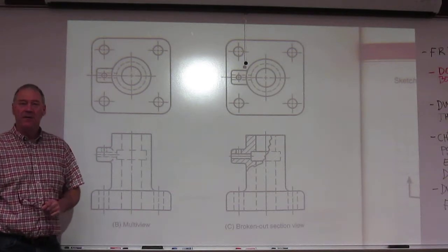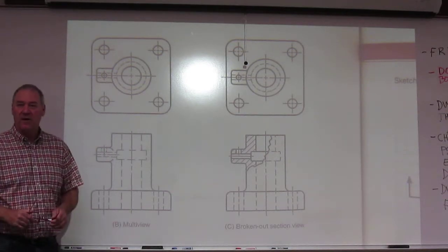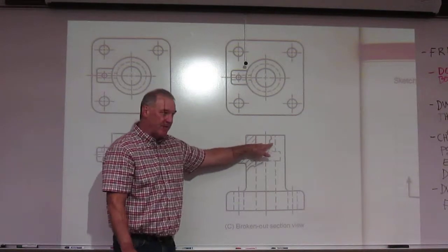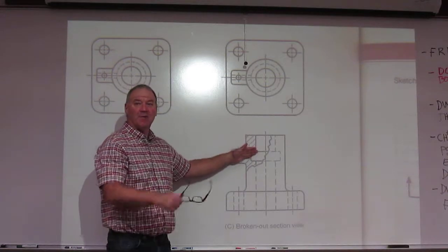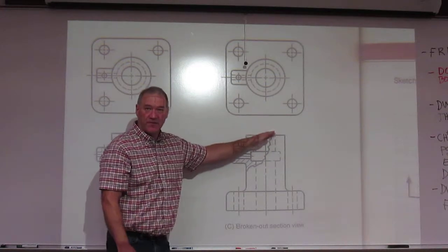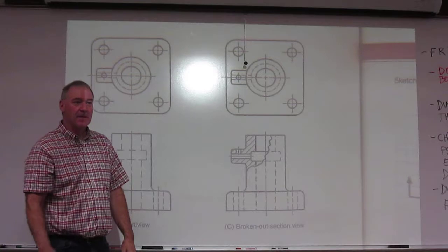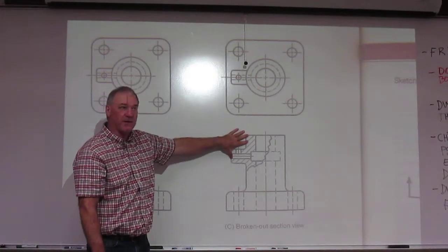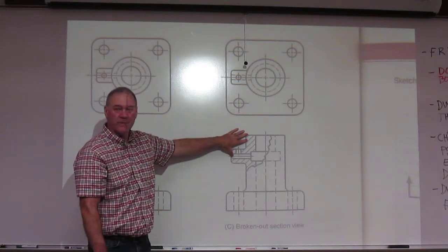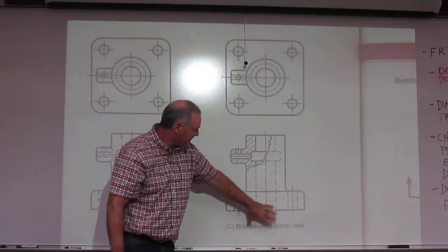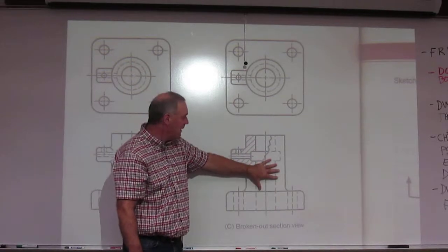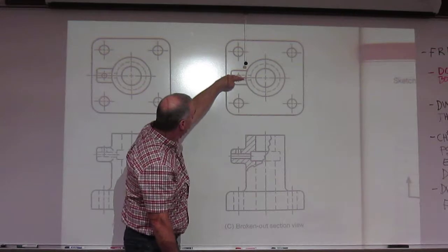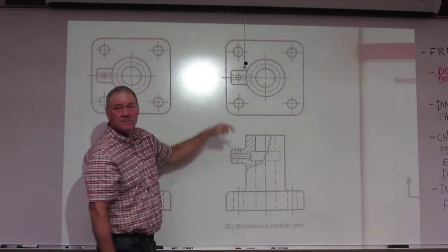There is no cutting plane with arrows on this. We use the short break line, and you see it right here. Remember, this is a very thick line, hand-drawn or made to appear as the material would normally break. We're not given a view because we are then going to section right on this view. So as we look at this, it's standard orthographic projection through the whole object. We come up to our short break line, and now we are sectioning right through this area.